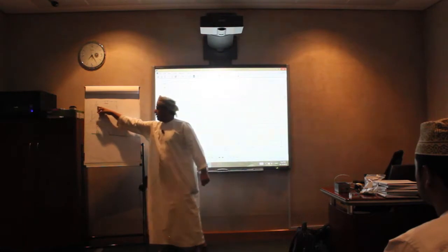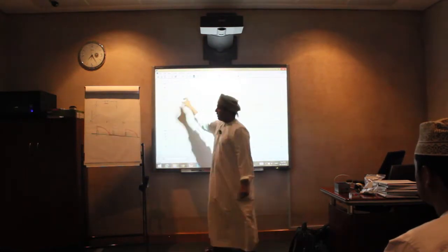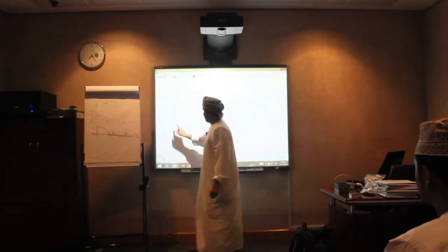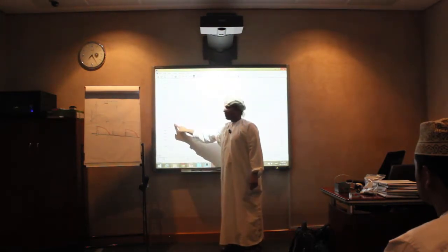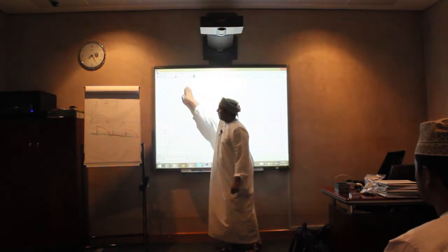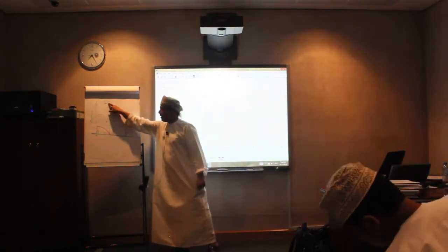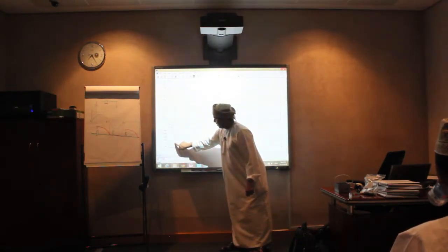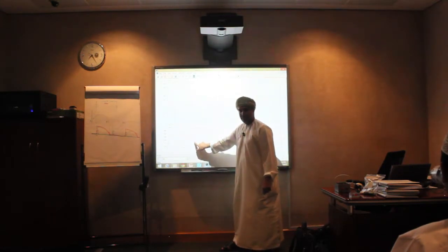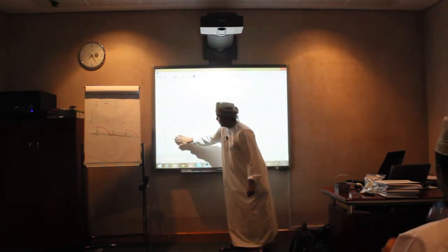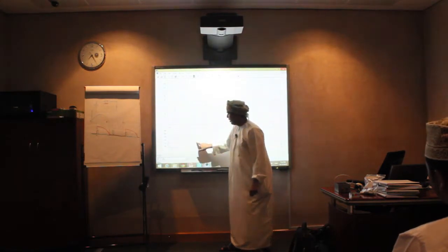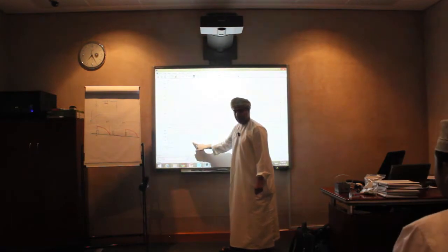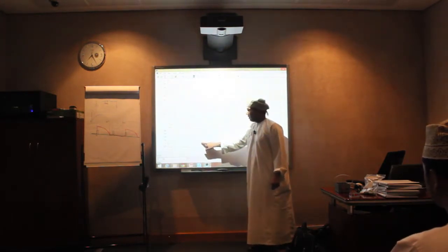This is the input signal, which is here, and then I'm sending this signal to the gate at this time, which is at 45. So at 45 exactly, while this thyristor is in forward bias, it turns on. Therefore, the voltage is reflected here, and you can see that voltage, which is exactly between 0 and pi, appears here, and in this mode here it is 0.